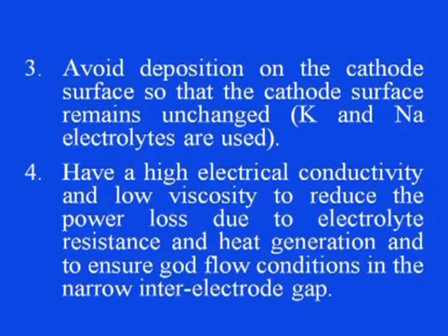Then number 4, it should have a high electrical conductivity and low viscosity to reduce the power loss due to electrolyte resistance and heat generation, and to ensure good flow conditions in the narrow inter-electrode gap. Number 5, it should be safe, non-toxic and less erosive to the machine body.